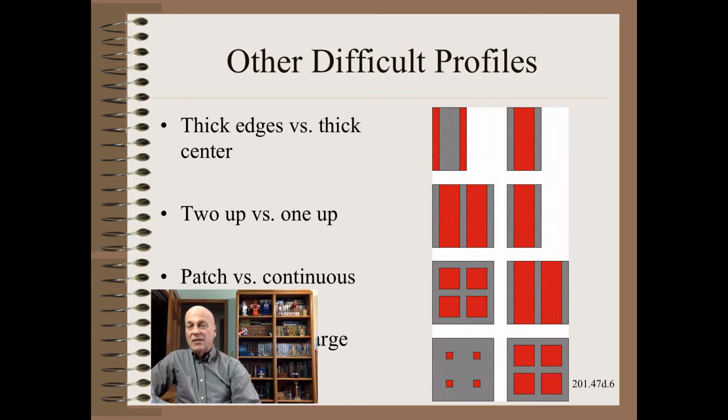Similar to the edges versus center problems, we have 1-up versus 2-up. Two lanes greatly risk wrinkling and registration issues. Sometimes, as we discussed in great detail in Web 101, these clips and elsewhere, it may be much easier to go fast than it is to go wide. For sure, this is the case from a purely web handling perspective.